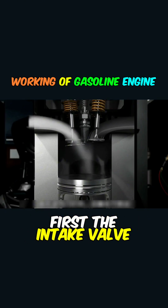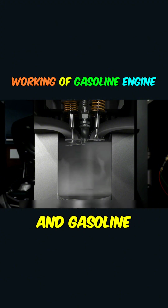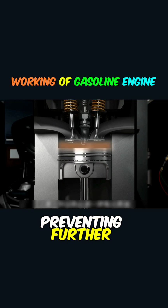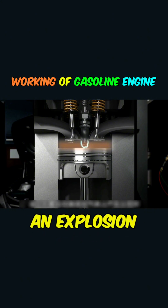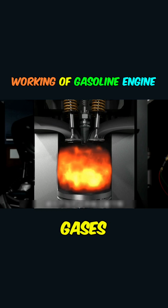First, the intake valve opens, the piston moves downward, and the mixture of air and gasoline flows into the cylinder. This is the intake process. The intake valve then closes, preventing further inhalation of fuel and causing the mixture to be compressed at high temperatures, which is called compression.